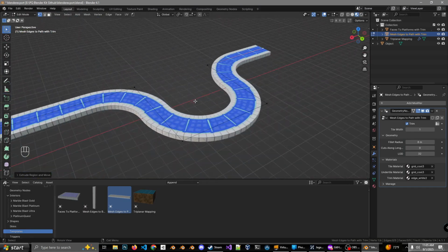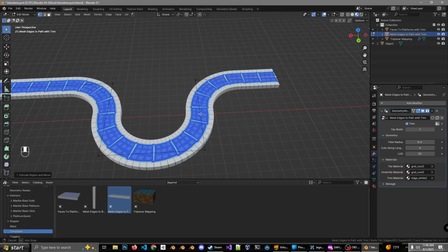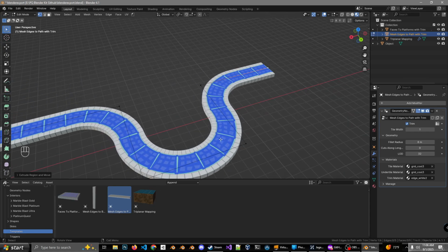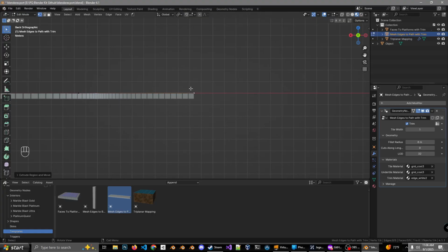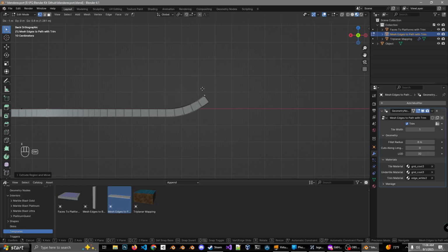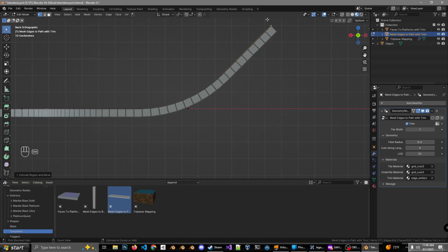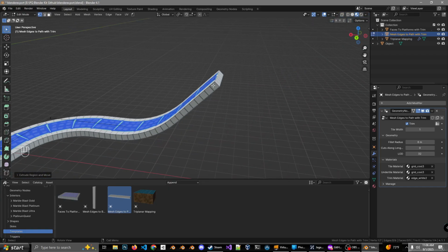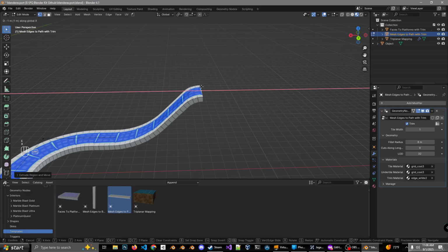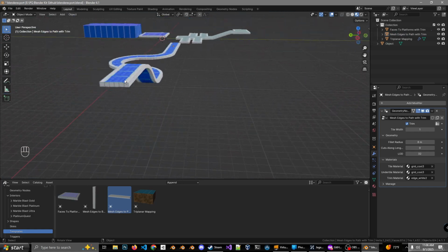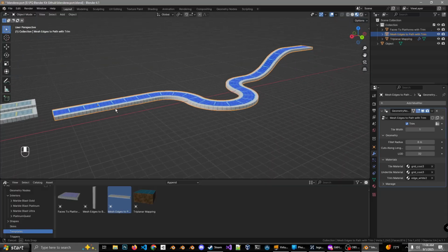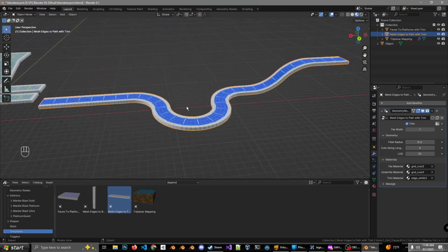This is by far my favorite tool to use with this program, as it makes making curves far less of a hassle than it needs to be. You can of course do this diagonally as well. So if we go into orthographic view again, press E, and let's do it by -5, -5. Now let's do another extrude. Press E. Let's work on the X-axis. -10. There you go. You can do quite a bit with this tool, and it just makes making curves so much easier.